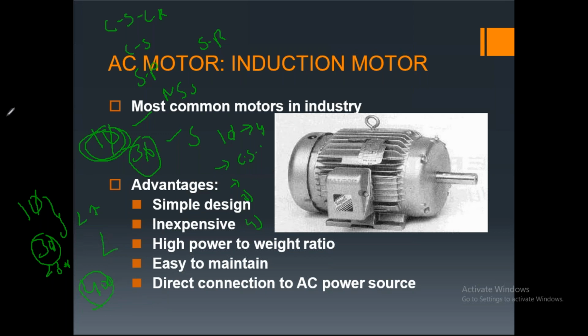So how? It means the three phase voltage is equal to √3 times the single phase voltage. If you multiply this √3 into 230, then you will get 400 volts. √3 into 230. So this is the value we can get for the three phase voltage.